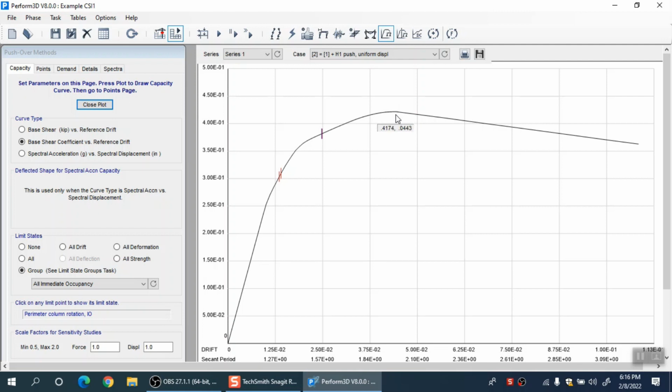So even if you exceed this IO level, even then you are safe, because you can rely on that additional ductility, right. You can also get an idea about what will be the peak displacement beyond which the structure will become unserviceable, and what will be the peak level of force which when applied the structure will become unserviceable, right.